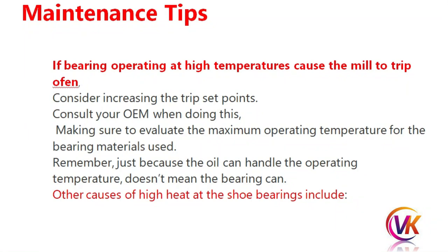Consider increasing the trip set point. This is not recommended, but you can try. But before doing this, consult your OEM, making sure to evaluate the maximum operating temperature for the bearing material used. Remember, just because the oil can handle the operating temperature doesn't mean the bearing can.